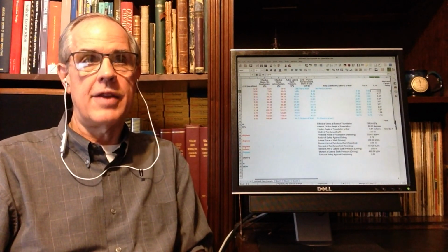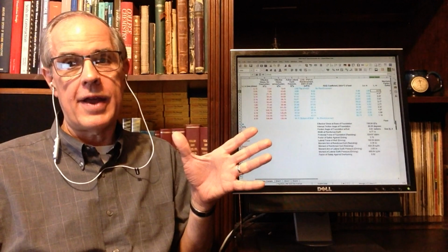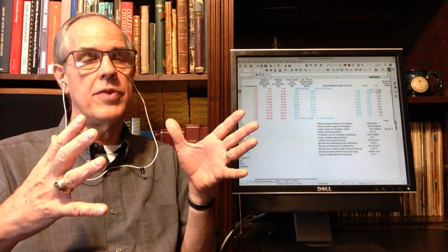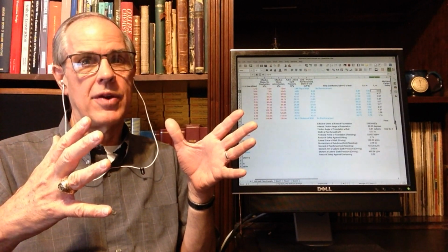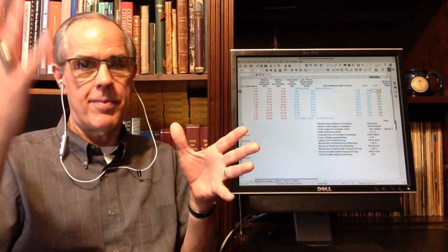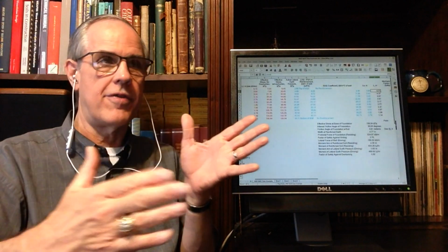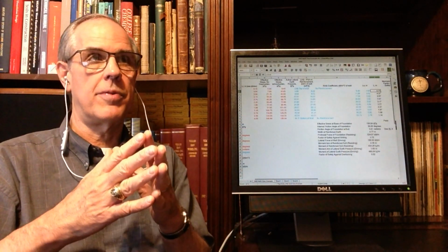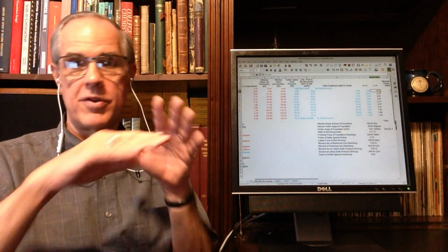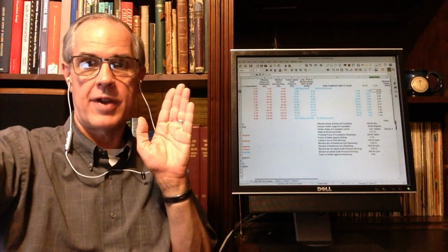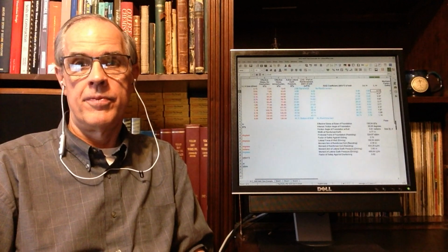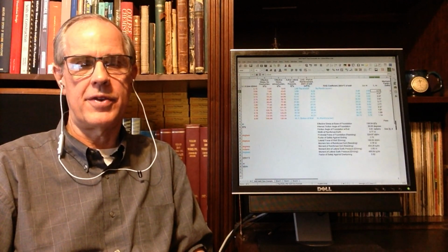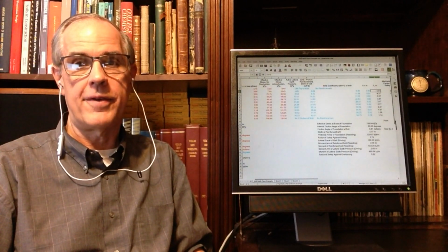Also, in many cases, for example if you're doing an overpass with an MSE wall, chances are you're not going to accomplish anything by just stopping it. You're going to want to continue. In fact, if you've got two facing MSE walls, it's very possible that the two strips will not only face each other, but you could actually lay one strip out from one side to the other. So there are not as many advantages in cutting back on reinforced backfill as you think there are.